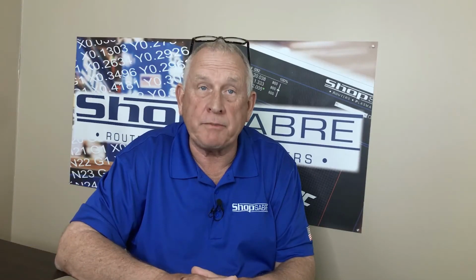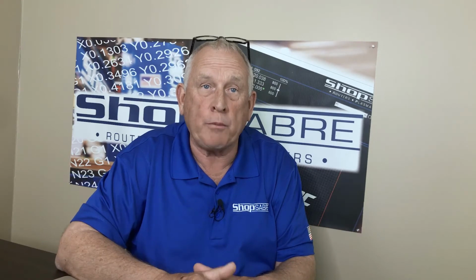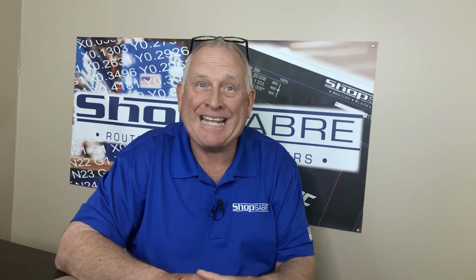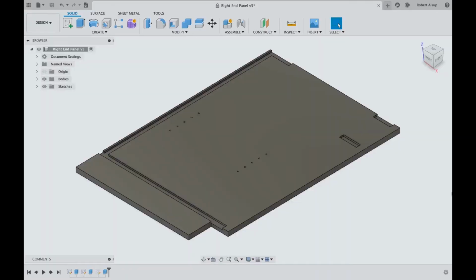Now that our part has been created in the design workspace, the actual toolpathing functions are performed in the manufacturing workspace. The first step is to figure out where the part is going to fit in the stock. That's done in a process called setup. Let's take a look. Okay, we've got our part modeled. Everything's fine. Now, let's talk about how we make it.